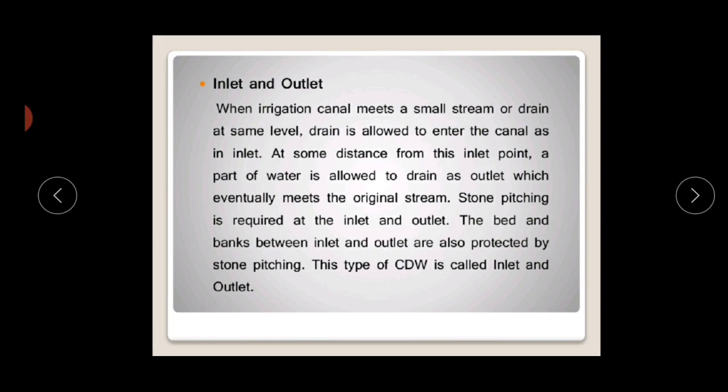But when the drainage discharge is higher, or if the canal is small so that the canal section cannot take the entire drainage water, an outlet may sometimes be constructed to escape the additional discharge at a suitable site, a little downstream along the canal.